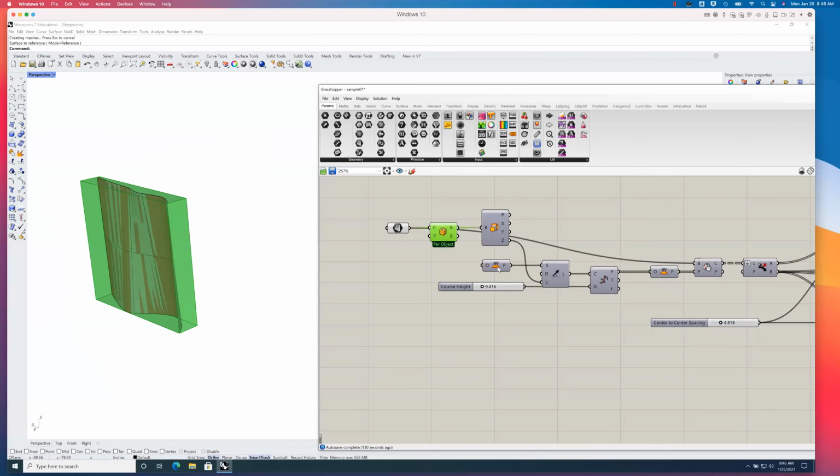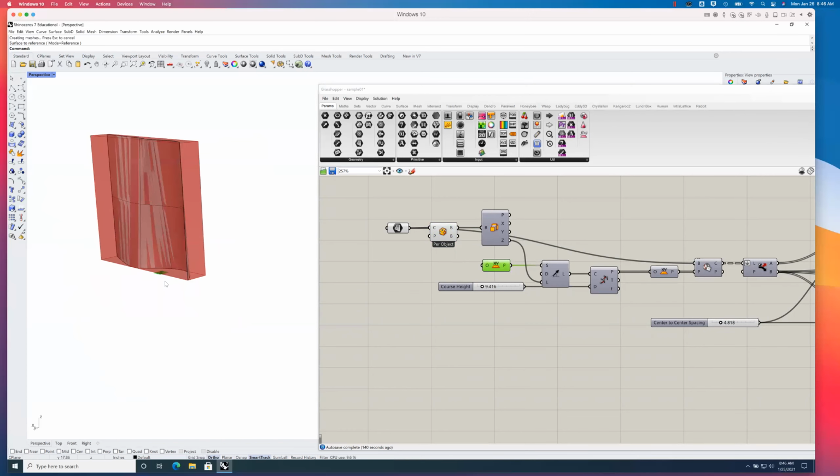I'm going to use that. And I'm going to create a plane at the 0, 0, 0 point. I'm going to create a vertical line projecting upwards from that plane, right? And its length is going to be this Z dimension. So I'm going to basically draw a line that's exactly as tall as the surface that I referenced in.